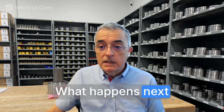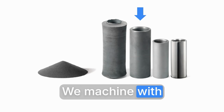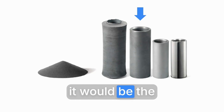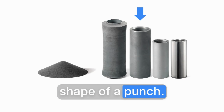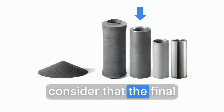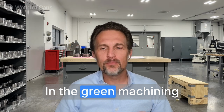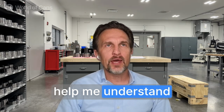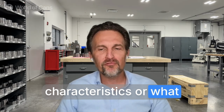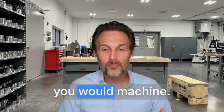What happens next is what we call green machining. We machine with a CNC lathe what it would be the shape of a punch. This shape has to consider that the final size after sintering would be much smaller. In the green machining, help me understand exactly what characteristics or what features of the punch you would machine.